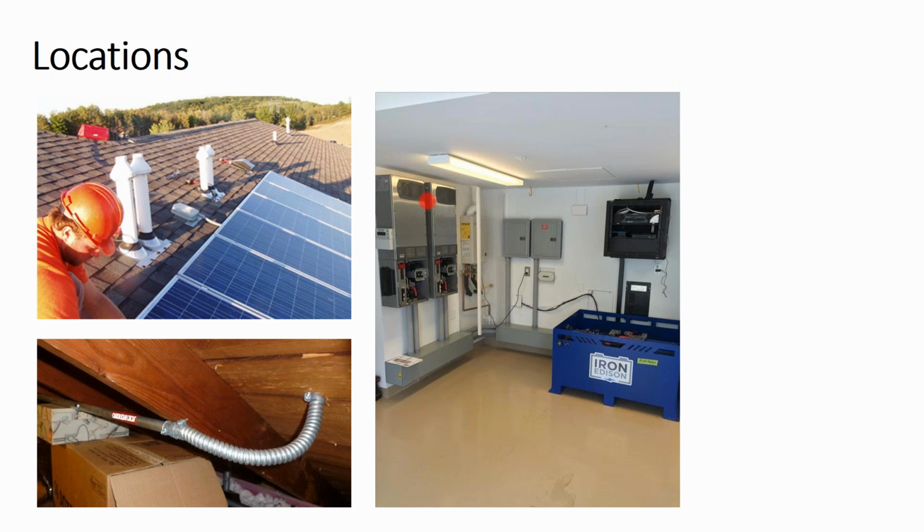I've seen it on a porch where you have underground cables coming up from the earth and landing on an inverter on the porch, and you open up the inverter and there's water sitting in the bottom of it because the inverter is watertight. And so it's trying to keep water out, but it's also keeping water in. And so you might, at that point, have to drill a weep hole into your inverter. You might find yourself asking, well, I'm supposed to have a weatherproof inverter, and is the only solution for me to drill a hole into my casing to let the water out?